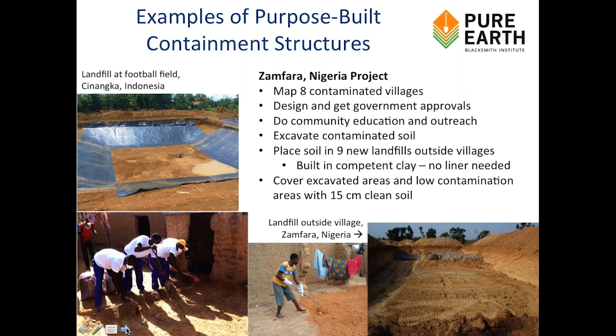You can see on the lower left the workers excavating the actual soil. They would put it into bags, load it into the trucks, and bring it over to the nearby landfill where it was deposited, as you can see at the far end of the site in the picture on the lower right, and then compacted and covered. And then all the contaminated material was covered with clean soil, which is the bottom picture.